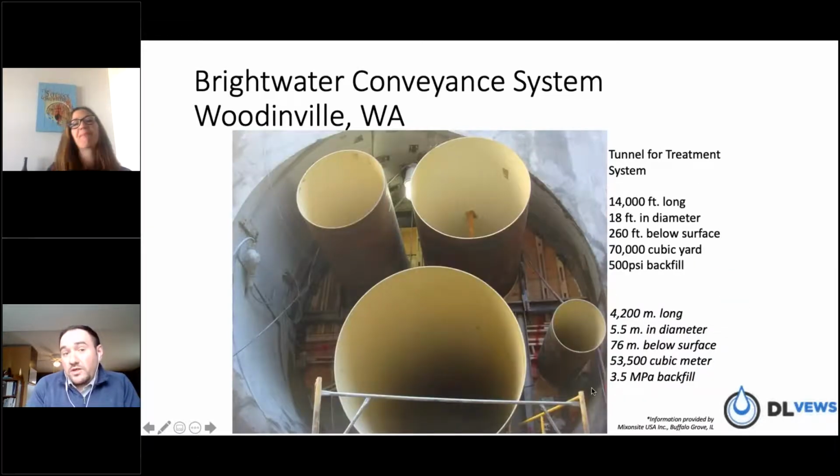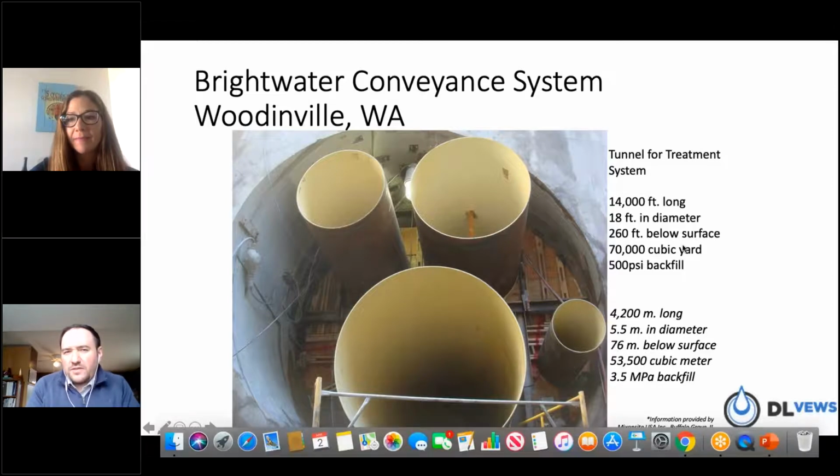Okay. So this is one of the projects I was referencing earlier when the question was asked, which was great. What was the biggest volume? There was a question along those lines. I was not directly involved in this project, but through mutual colleagues, this is a case study that we have. Behind that wooden and steel bulkhead in between those four pipes is a massive annular space. And that was pumped, as you could see. 70,000 yards of volume that we had to fill. So that was done through the utilization of cellular concrete. Nice. That's a huge project.